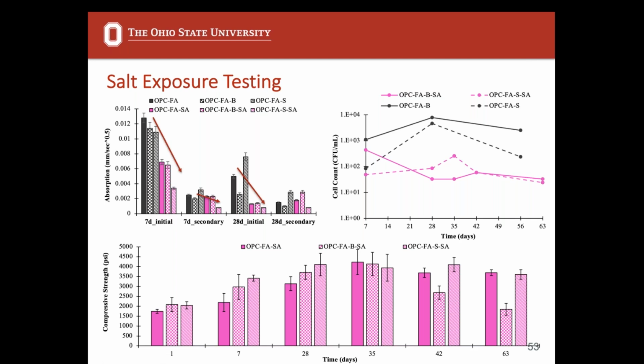And then we also tested our samples. We cured them for 28 days. Then we exposed them to a salt solution for 2 days. And then we cured them for another 28 days with curing solution, trying to track what was going on as far as absorption and cell counts and compressive strengths again. And so we see a reduction in absorption. So we actually had an improvement from the bacteria after exposure to salt, but we again saw a pretty steep drop in the number of bacteria that were alive after exposure to salt solution.